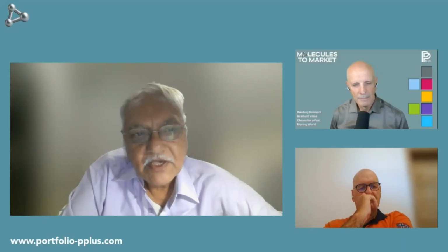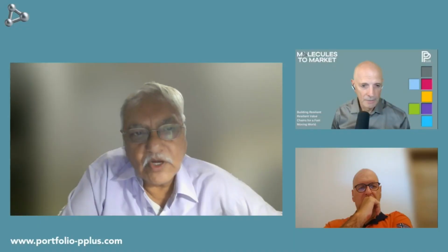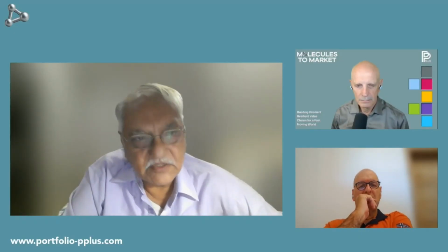Now in India, when we finalize a configuration, as part of the screening study itself, our tendency always is to boil down or screen it down to at least two options, maximum two, because beyond that, it is very difficult to do economic study, because every time from 2 to 1 when I'm going to come, I have to do some kind of economic study. At this stage, we do only order of magnitude estimates.